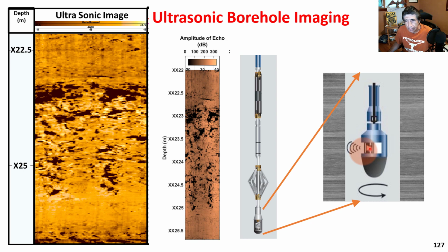So we send an ultrasonic signal. It's an acoustic signal with high frequency, and that signal is sent over to the formation. When it hits the formation, it's reflected. So what the measurements sense is the time of flight between when the signal is emitted by the ultrasonic source and when the signal is received back by the same piezoelectric transducer.